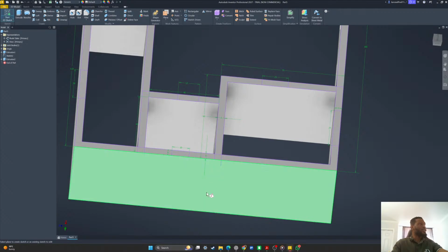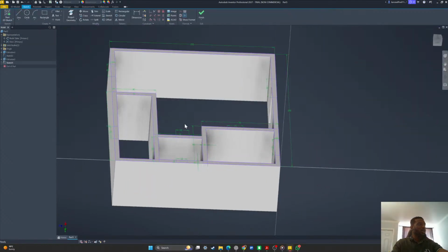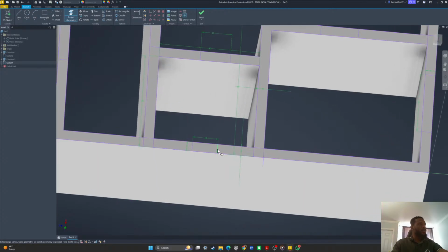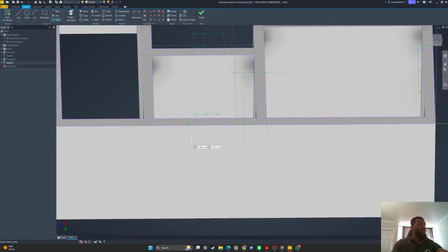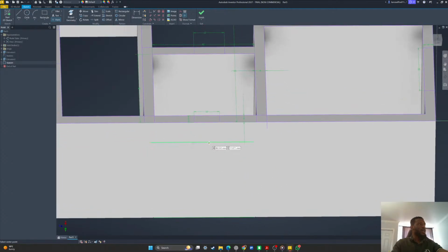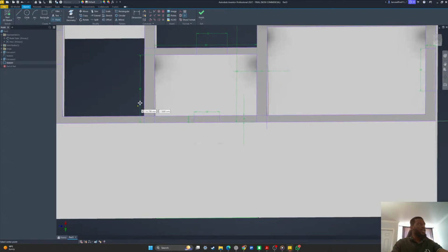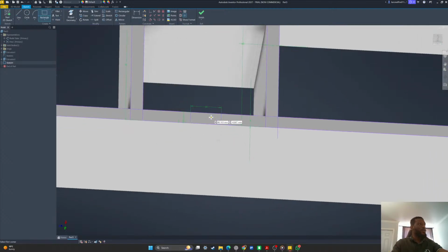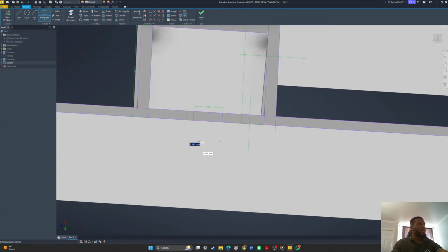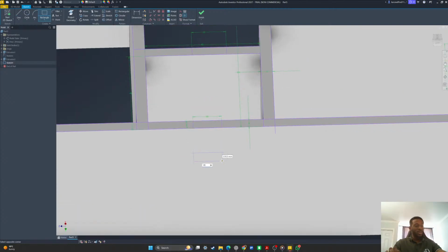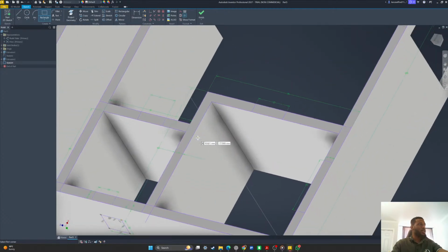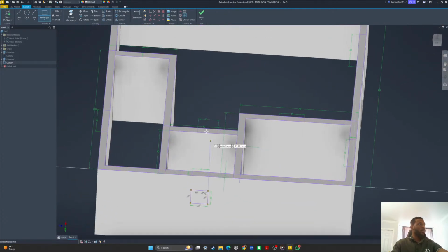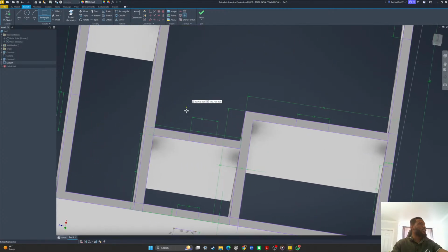And then we'll click on sketch, just like we did before. Project this geometry, and this is going to be a window of 10 by 10, because we have made it 10 mm. So I'm going to say 10 by 10, and there we have the window right there. We don't have anything else on this.